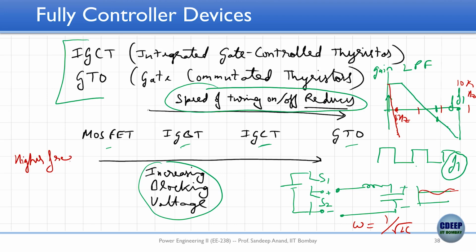Higher frequency can lead to smaller LC, and this is the reason we would prefer to have a higher switching frequency.